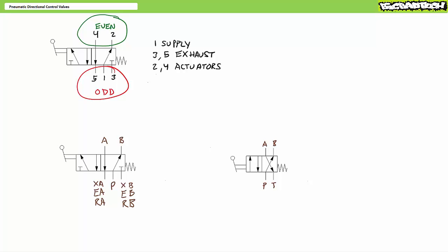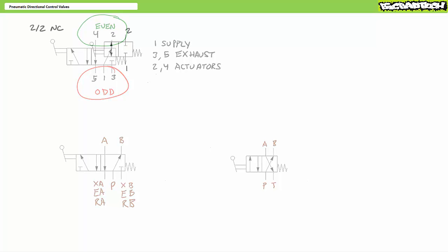For now, just realize a 5x2 directional control valve, i.e. a valve with independent exhausts for each actuator port, sure makes it a lot easier to meet these challenges, whereas a 4-port valve, one with a shared single exhaust, would only complicate it. Additionally, we'll examine accessory components like quick exhaust valves in later lectures.